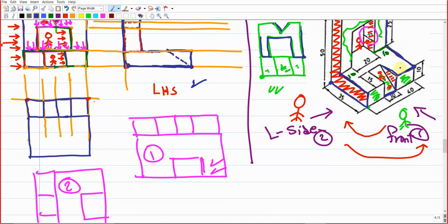This is gonna give us all of this face, but we have to form in the middle the inclined surface. The inclined surface should have a length. This length should be 15. So from this point of view, measure 20 because this is 10 out of, I'm sorry, it should be 15. 10 out of 40 gives 30, so this distance should be 15. So from this point, you're gonna measure 15. Then you're gonna go inside with 15 as well. Then you're gonna move with 10 to the left and 15. So this rectangular shape is gonna give us the inclined surface.